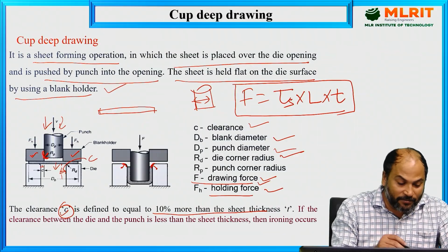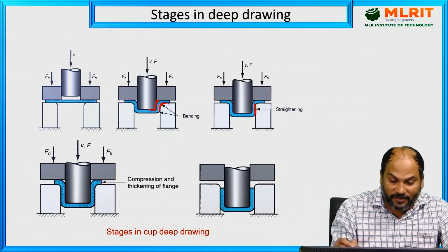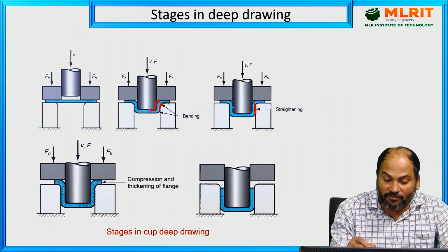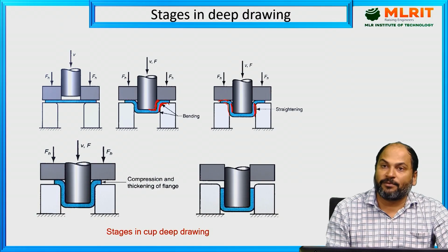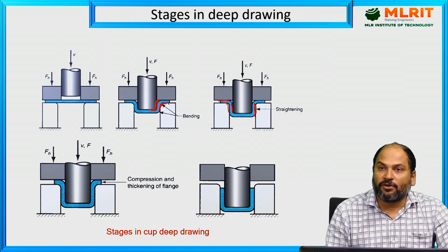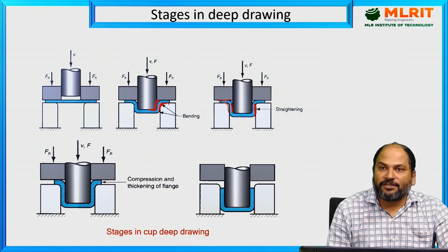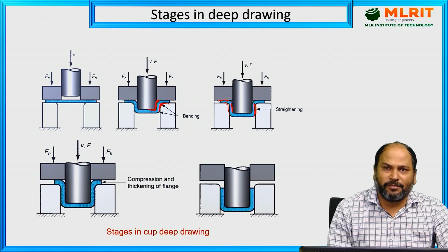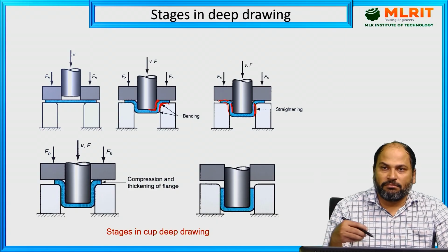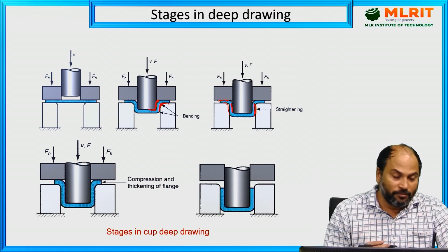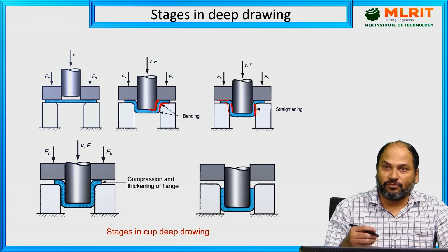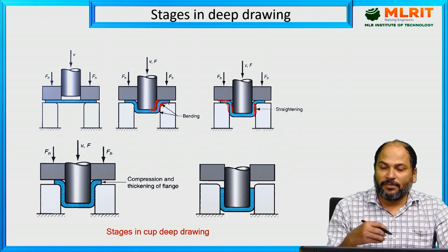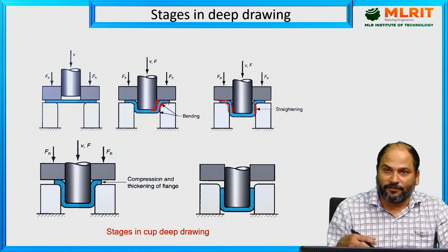Wherever the part is in contact, obviously there will be friction. Here it is in contact, we can see here it is in contact. Wherever it is in contact, because of that there will be friction. And if friction is there, no need to tell, it will create problems in material flow. So different kinds of lubricants are generally used over there to eradicate the effect of the friction.